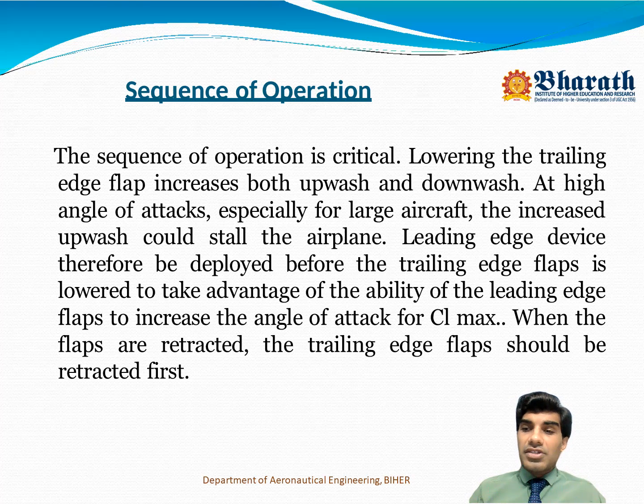Therefore, the leading edge devices are deployed before the trailing edge flaps are lowered, to take advantage of the ability of the leading edge devices to increase the angle of attack for CL max.